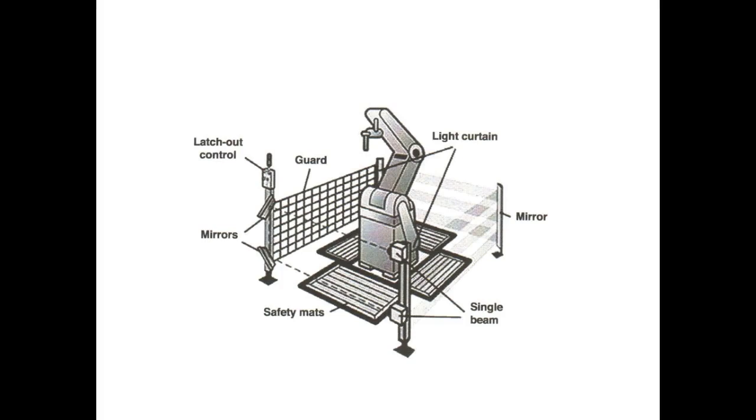So what's nice about this, it allows the cell to be open. That means I can have a cart or something bringing something into the cell, right? You understand? Light curtains usually are set up in different spaces. So when a cart comes in, they can disable a certain section of the curtain and leave the rest of it in place.